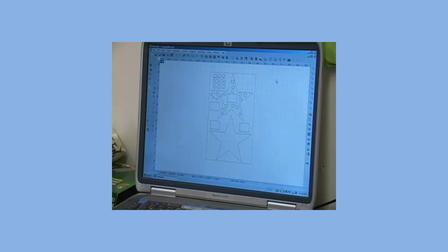Okay, everything we placed inside will be a female piece, and everything on the outside will be a male piece. So we will create our female toolpath first and then our male toolpath. So we have to select our objects. So I'm going to draw these puzzle pieces. Press Shift Control to select more. I need these. I also need to have these. I also need the inner square or rectangle.